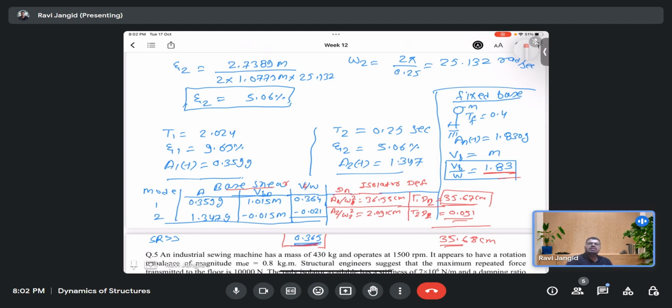So you can find out the damping first, rather than doing that calculation first. Pull that model and leave it, and record the vibration of it. Using that you can find out the logarithmic decrement, and from that the damping. Or if you know the damping for aluminium, then you can find out the modal values and solve it. Damping you need to take into picture, otherwise you will not get it right, because in reality there is always damping, nothing is ideal.